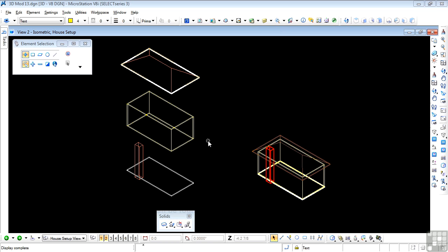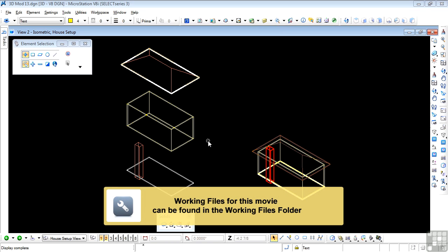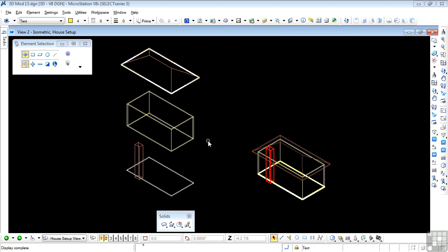Whereas the previous tool displays a perspective through simple view manipulation, MicroStation's camera tool uses a virtual camera to generate a perspective from any location in relation to the object. The camera also has a selection of lenses, ranging from fisheye to telescopic, and it's always in focus. Now we're discussing basic camera controls here in this video, with more detailed information being presented in the next video